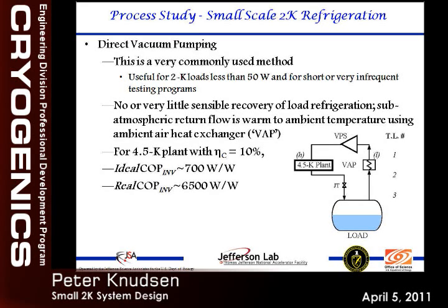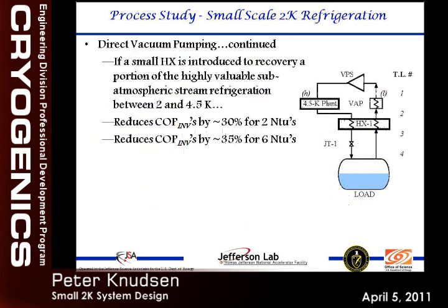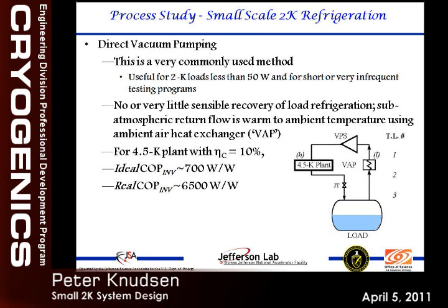All right. So the first 2K configuration that we should look at is the most commonly done, and it's what we normally know as direct vacuum pumping. In this case, what's happening here? This is the 2K bath. We're going to pump on the 2K bath from the vacuum pump right here.